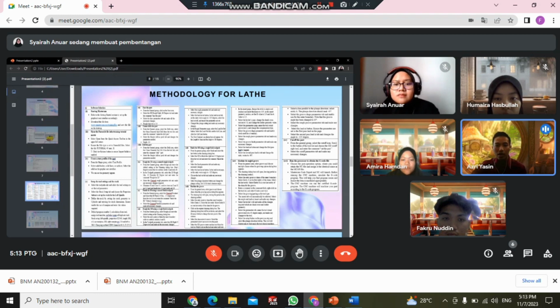Use stop for outer boundary, plunge parameter also changes. After changing in the chaining box, select the OD finish right tool, 35 degree tool, change lead in/out and the lead in angle, and the plunge parameter also changes. After that, for groove choose chain, select the entry point or change the inner boundary, select entity A. From there, we need to change the arrow to move, which is the green arrow, and select the OD groove center medium tool from the tool list.